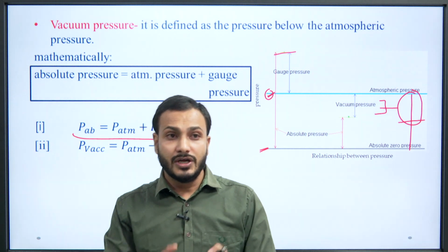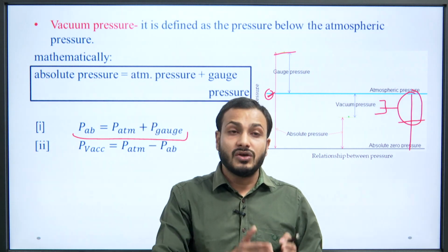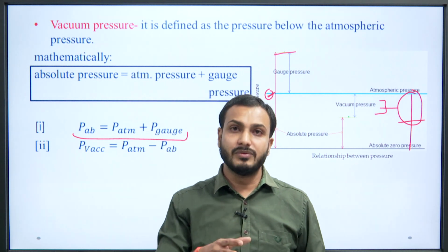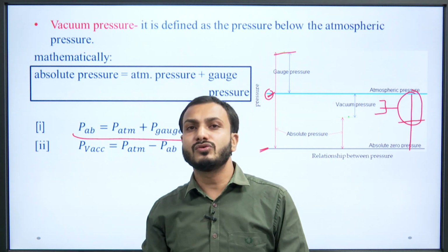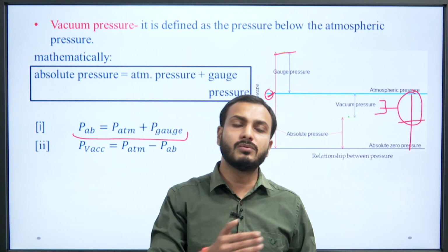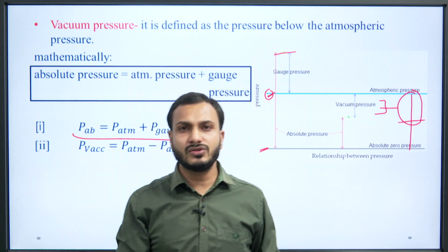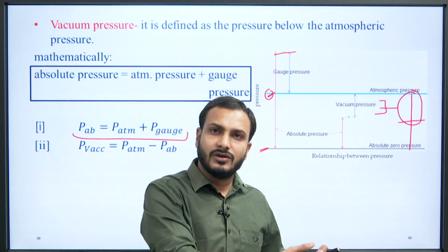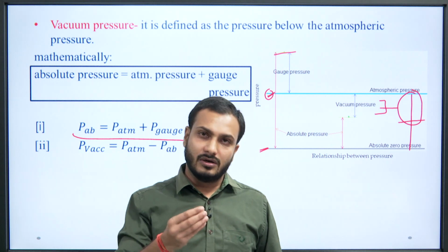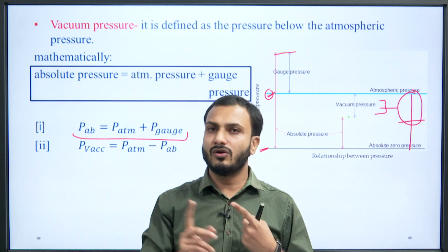Okay, so today we have seen the types of fluid and what is the Newtonian fluid, what is the non-Newtonian fluid. Newtonian fluid, once again I am telling, which obeys the Newton's law of viscosity. Okay, means what? Tau is directly proportional to shear strain rate, means velocity gradient, that is du by dy. और non-Newtonian में क्या हो जाता है? Which do not obey that Newtonian law, means what? Tau is not proportional to that velocity gradient, so that will be non-Newtonian fluid.